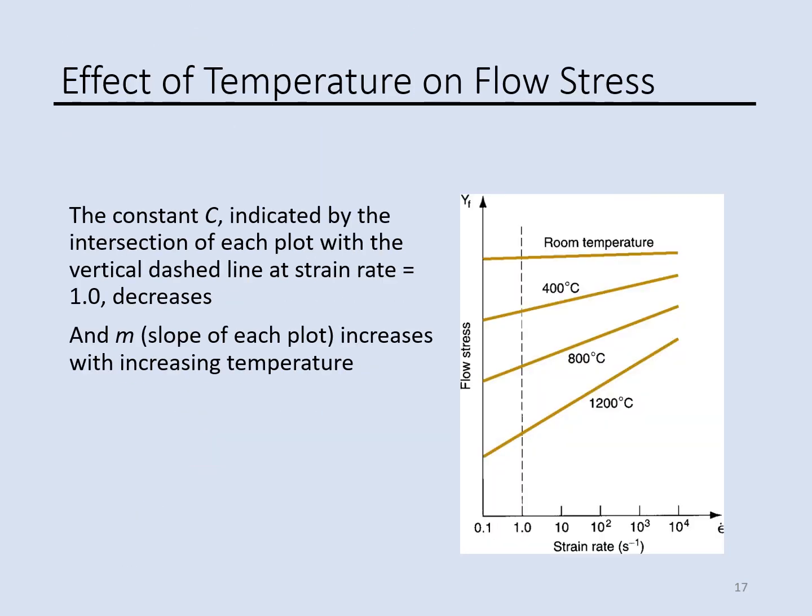Here we have a plot of flow stress over the strain rate. As you see, for this plot at room temperature, if you increase the strain rate, it means the ram or the punch moves faster at room temperature. The flow stress changes slightly. It doesn't change much.